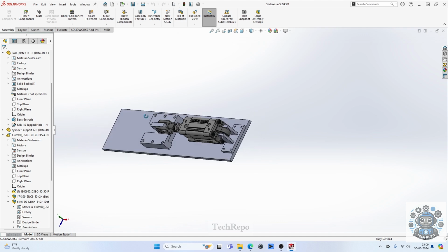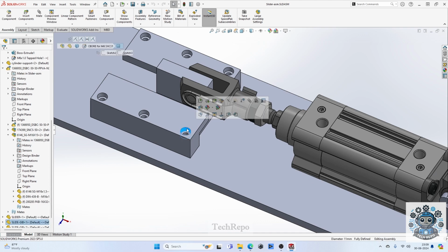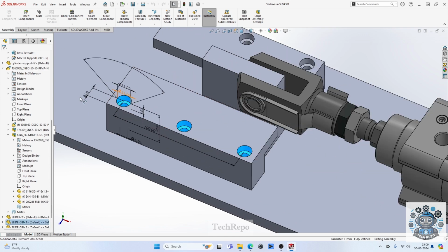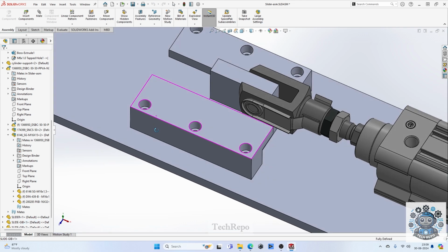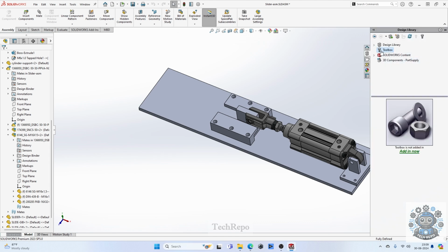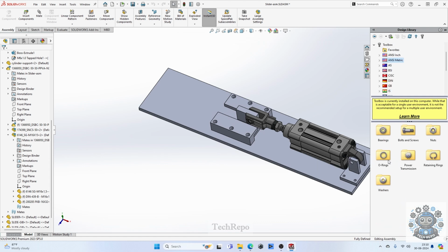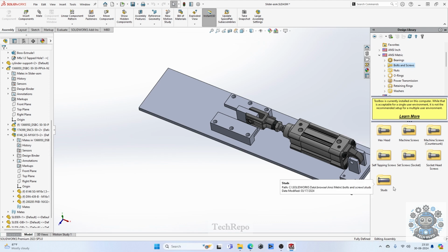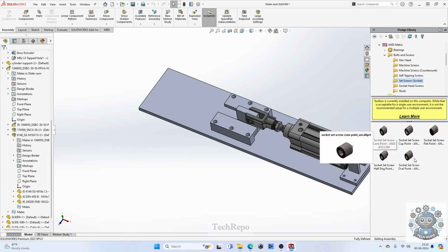As you can see, all the tapped holes are created already. Now this is the assembly, and see, I didn't edit the depth of the counter bore. It should be more. It's better if it's more, because then you can have a shorter length bolt. Okay, I think this would be better. There are two purposes for using a counter bore. One is to make sure the head of the bolt is below the surface, and the second is, in cases where you want the length of the bolt to be shorter, you can use that.